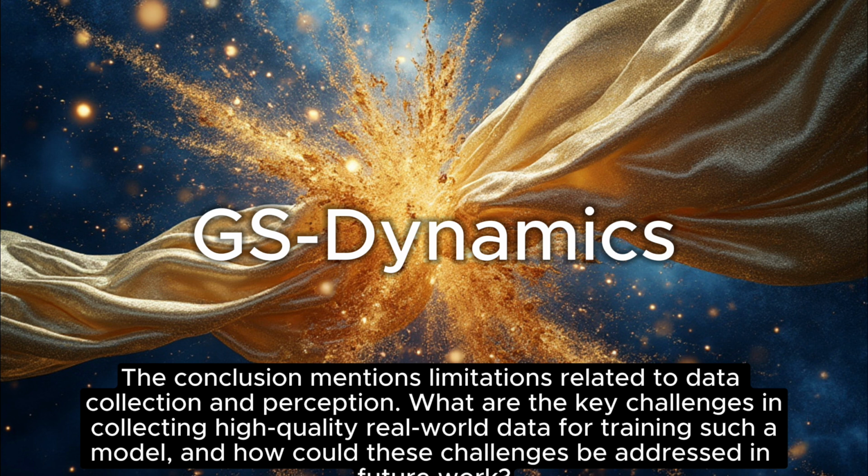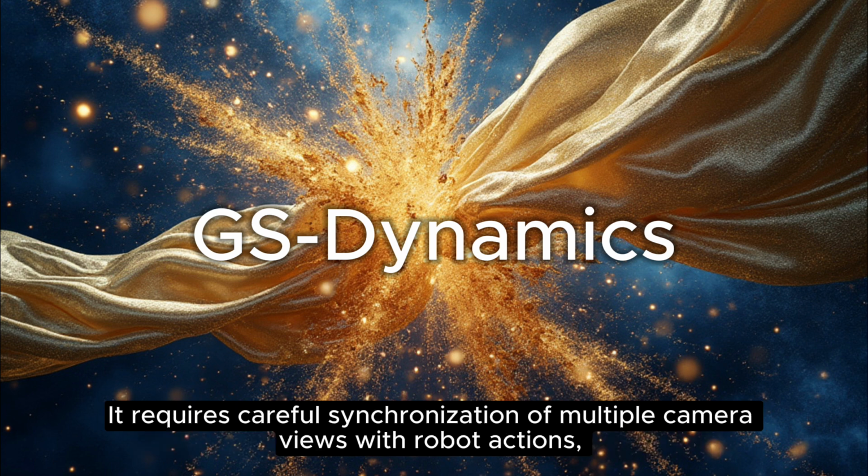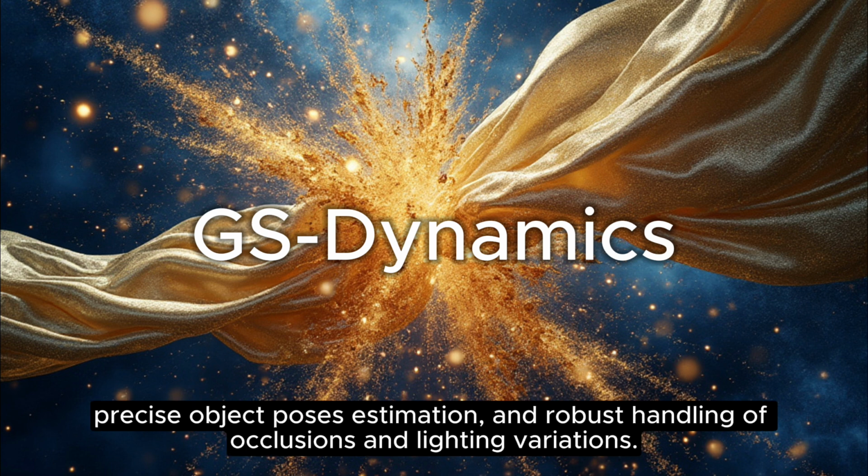What are the key challenges in collecting high-quality real-world data for training such a model, and how could these challenges be addressed in future work? Collecting high-quality real-world data for training this type of model is expensive and time-consuming. It requires careful synchronization of multiple camera views with robot actions, precise object pose estimation, and robust handling of occlusions and lighting variations.